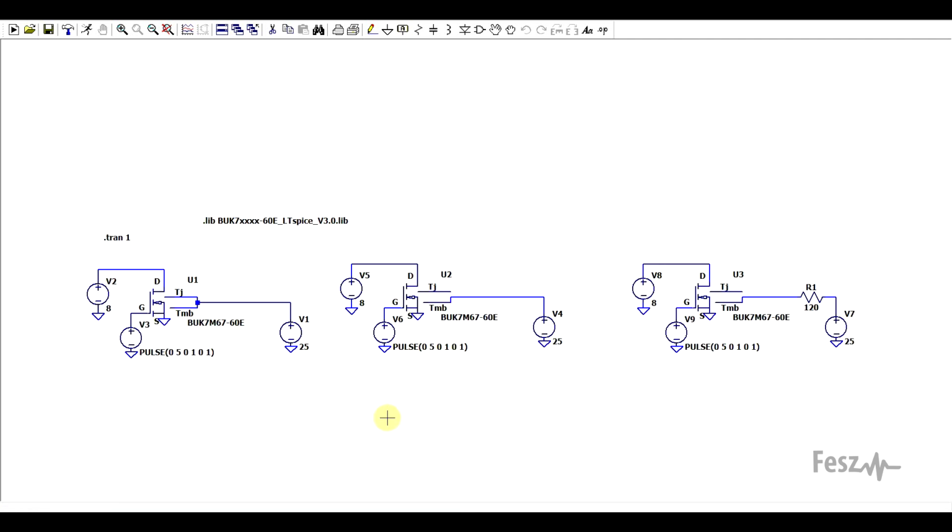Now, just to illustrate how this can be used and how it behaves, I made a few implementations. So you can either fix both the junction and solder point temperature to an external reference, so 25 degrees in this case. This will be more or less an ideal use case. You can set a specific mounting point temperature, so we just fixed this value. Or finally, you can provide a thermal resistance to the mounting board, and we'll connect through this to the ambient.